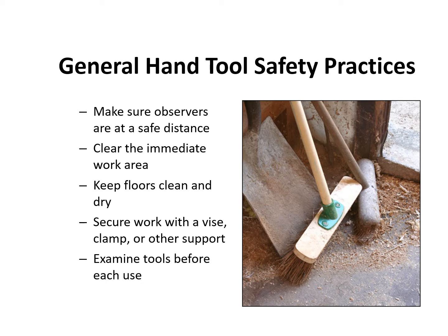Floors should be kept clean and dry to prevent slips or trips when using hand tools. It is important to have good footing. Secure the material that you're working on with a vise, clamp, or other support. If the material moves, you could become injured. Do not attempt to hold the material yourself. Too many injuries occur when this happens.